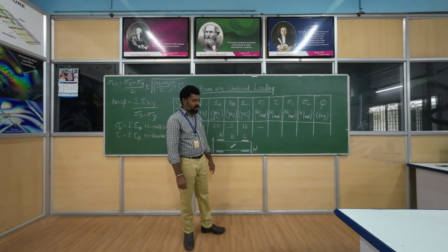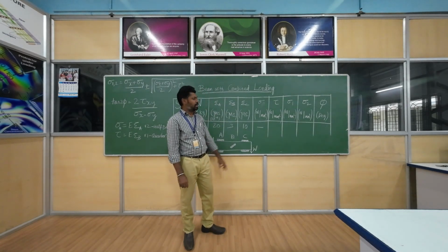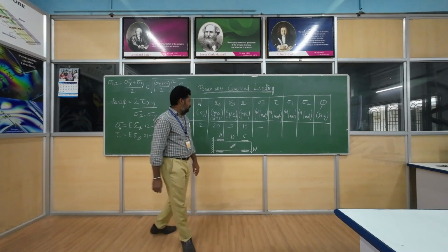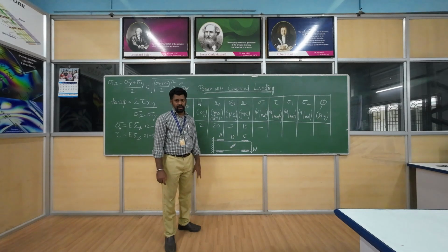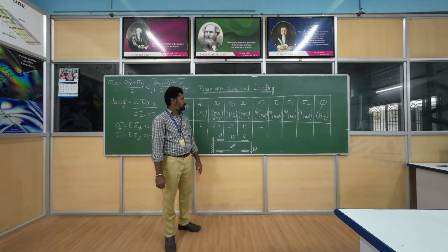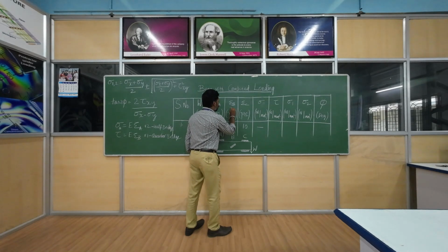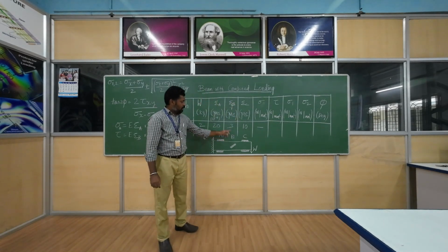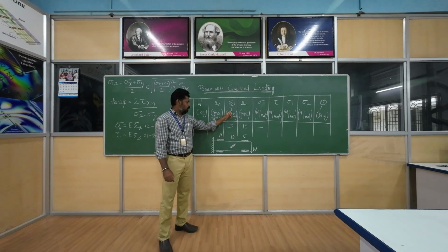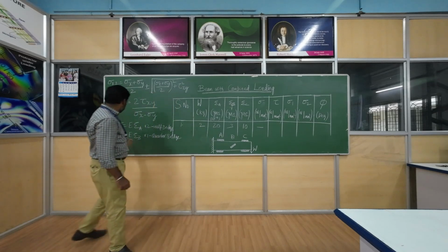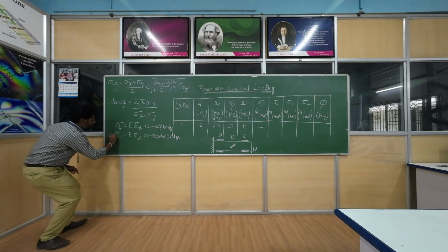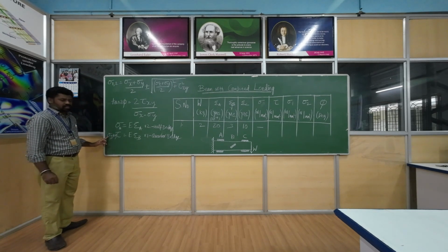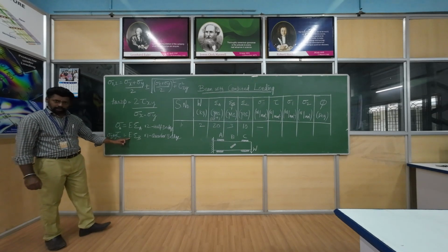Now what is next? We need to compute the shear stress, that is tau. As I mentioned earlier, at section B the strain gauge has been oriented at 45 degrees. This will give the shear strain. So you can write epsilon B or gamma. This is the strain we get from section B. We got 3 microstrain at section B. Again we use the same formula: you can write sigma B or tau, the stress at section B. Again we apply Hooke's law.